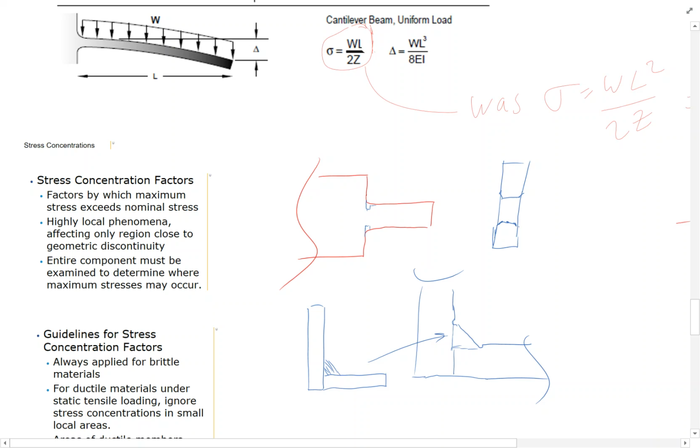They've got an enormous safety factor, 10 or 20, right? But the fatigue is what actually caused the failure. And when that failure occurs in a fatigue situation, typically it's catastrophic. I mean, it's instant and things just let go. But again, the stress concentration factor is caused typically by geometry, by a feature, where you've got maximum stress exceeding the nominal stress, or the average stress. It's a very local phenomenon. Again, it's typically connected to a geometric discontinuity of some sort, being a sharp corner, being an inclusion in a forging, being lots of things that can cause issues.